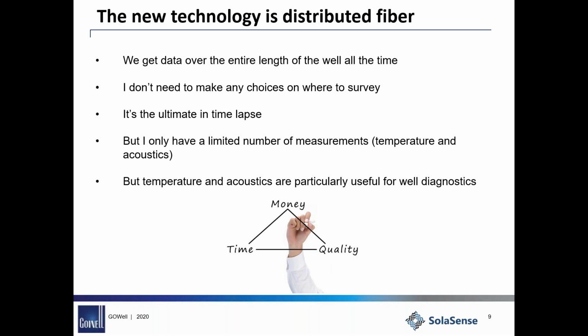These are sensitive instruments, these interrogation units, and they are subject to change if we have too much surface activity going on. And by that I mean they're sat in a shack and somebody opens up the door and you get a blast of cold air or hot air, depending on which part of the globe you're in, that chills down the reference coil or the instrument itself. And so I like the ability to have a good absolute temperature reference at the bottom of my fibre used to correct that temperature too.